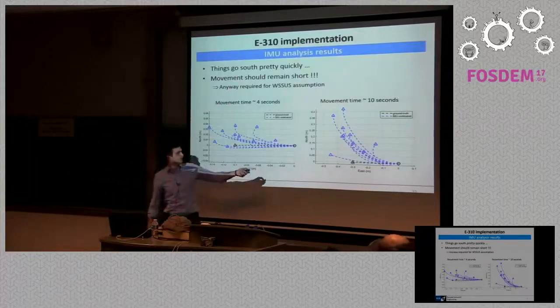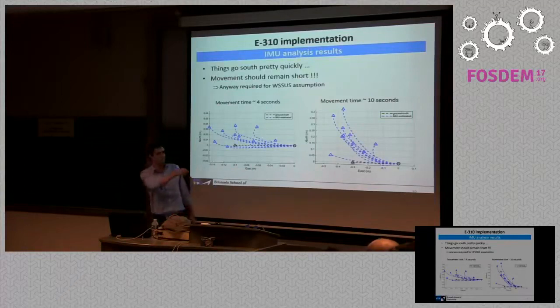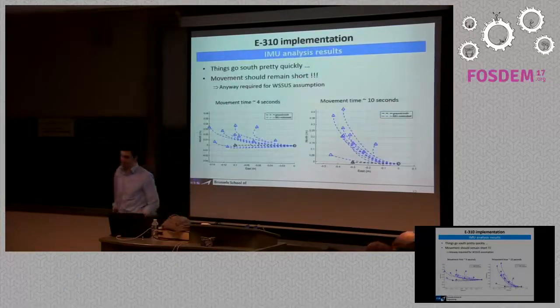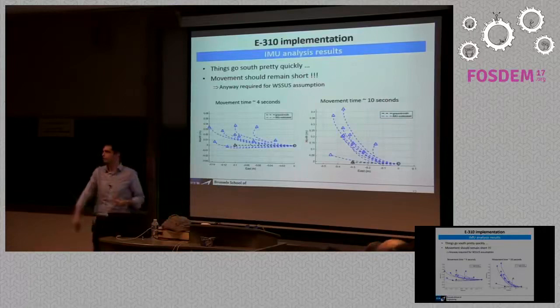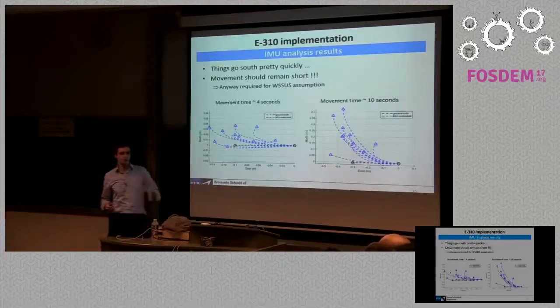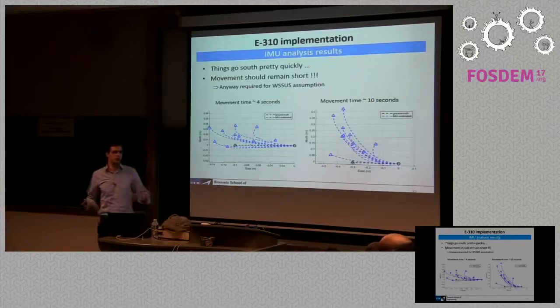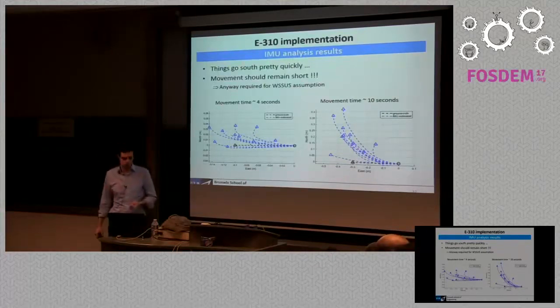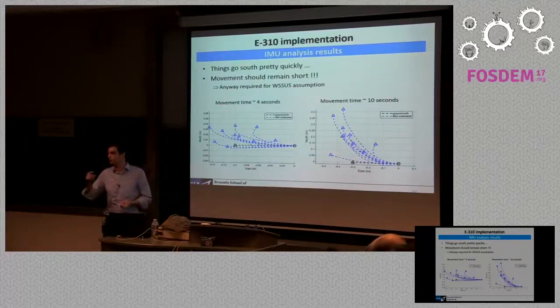When we go for longer runs, movement that lasts, say, 10 seconds, well, you can see that the error increases quite dramatically. We're almost at half a meter error here, right? This is why people don't use IMUs when they actually do dead reckoning navigation. You can see that the error is always going in the same direction. So there is some leftover bias after the calibration procedure. We did the calibration procedure on the day before the experiment, and on this type of IMU, the stability is really not that good. So you need to repeat the calibration before every run.